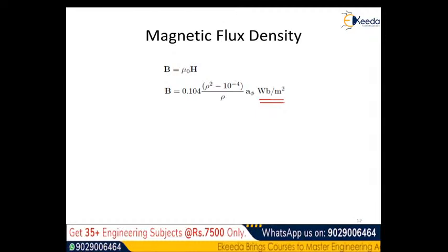Yes. Now, after determining the magnetic flux density, it is very simple to compute the total amount of flux here. So the total amount of flux for part A, designated by phi, with phi ranging from 0 to 2 pi, z ranging between 0 to 1 and rho ranging between 0 to 1.2 centimeters. We have phi, the total flux, equal to the surface integral, the double integral of B bar dot dS bar. The dimensions here we put on the integral notation.